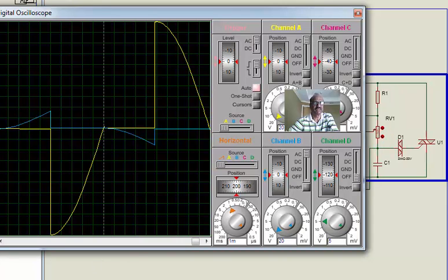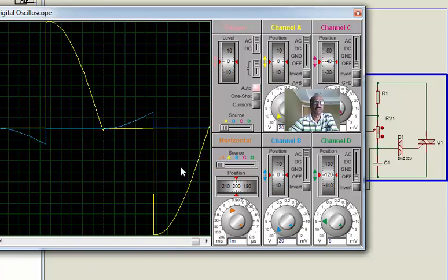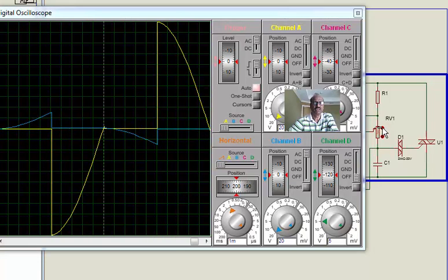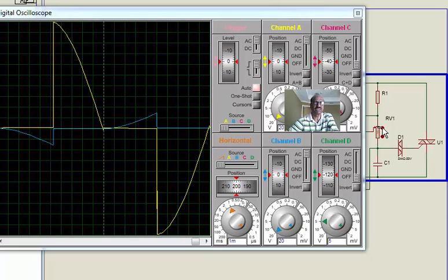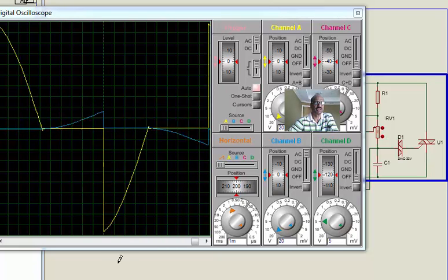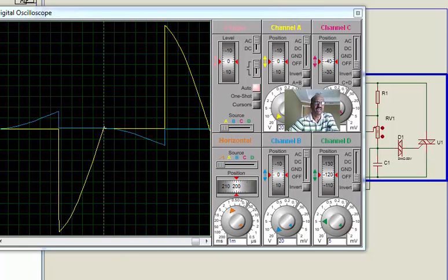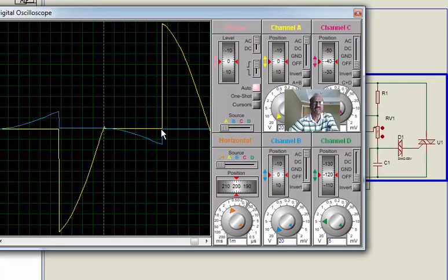And if we go on further increasing the resistance, you find the time is still increasing, and in the process, as the time goes on increasing, the delayed firing also goes on increasing. In the process, the power to the load gets reduced. And that is how we find that the lamp is operating with a lesser intensity.